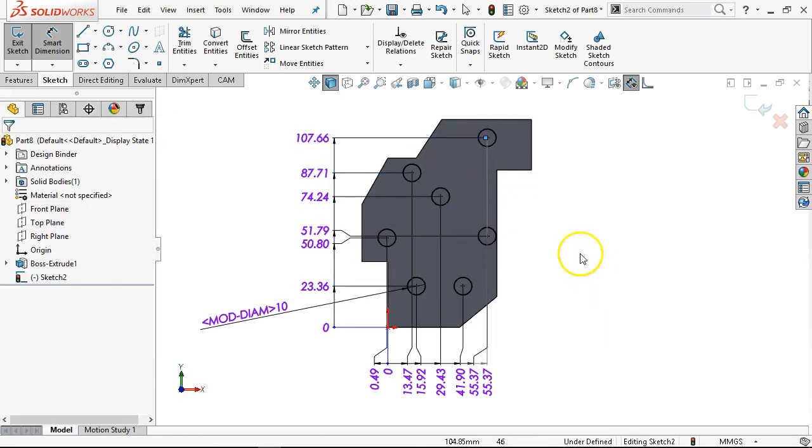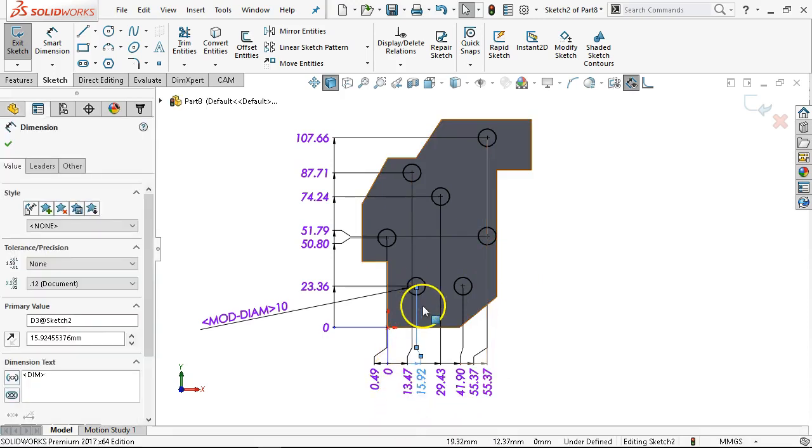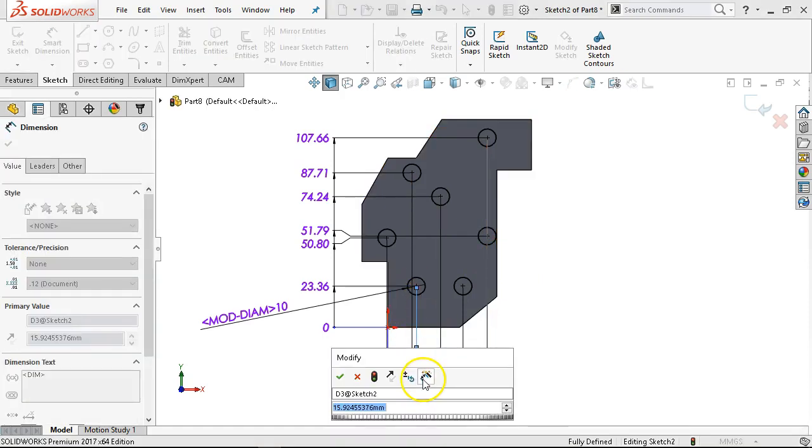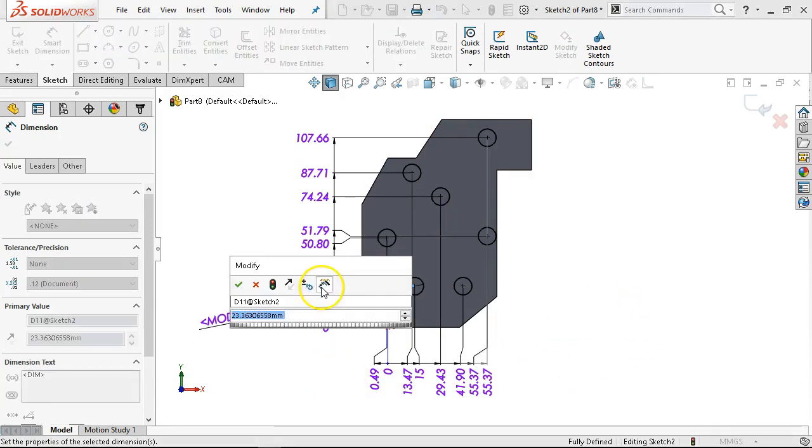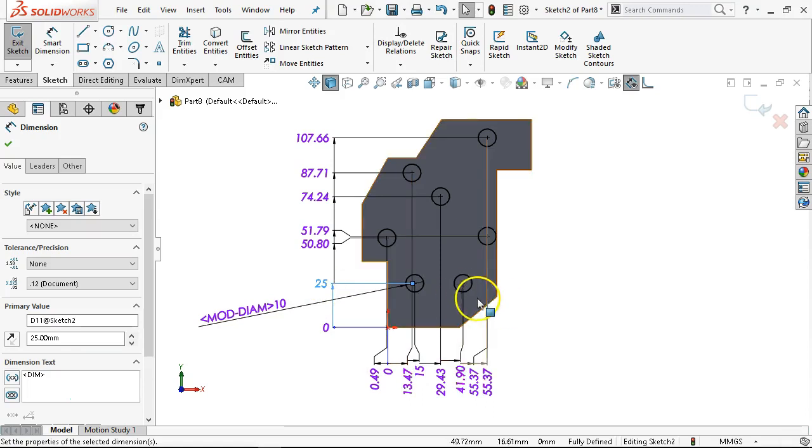So all I'm really interested in is getting them applied, and then we'll figure out which one's A3, so 15 and 25. So if I go to extension line and accept, and then what was it, A5 is 38.51.